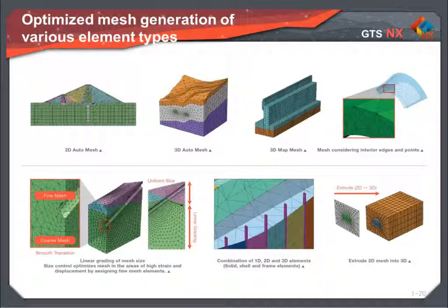And of course, GTS NX provides automatic and manual options to control the size of the elements in our model. We can define edges or global sheets to restrict the element size at areas of stress concentration.